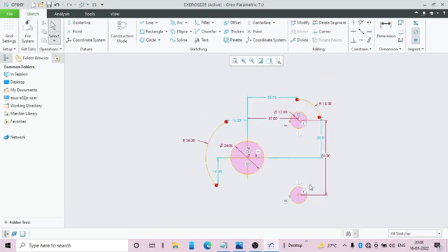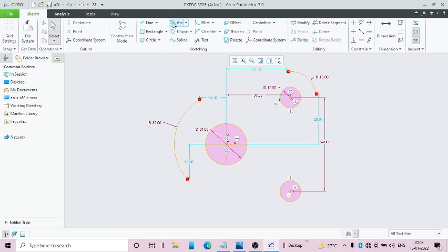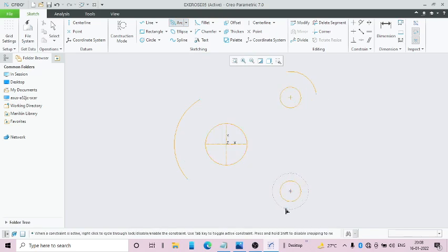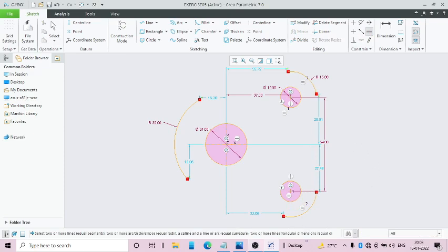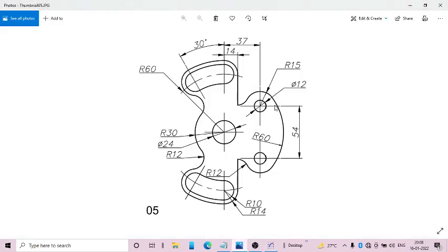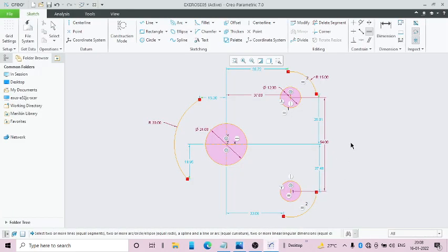So you can mirror it, but I think the sketching option will be much more comfortable. So let us select the arc option. Then let us draw another curve as well. And now we can give equal, these 2 curves equal. Okay. Now here there is an arc R60, and if it is not given, you have to assume that this is tangent. Okay, so draw the R60 curve.